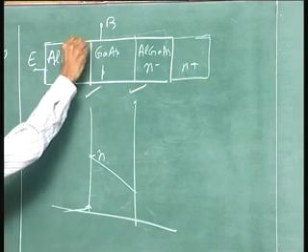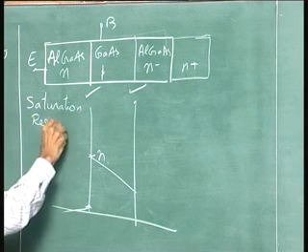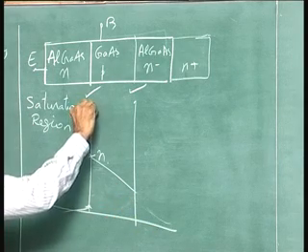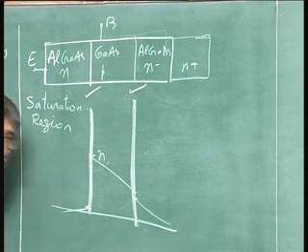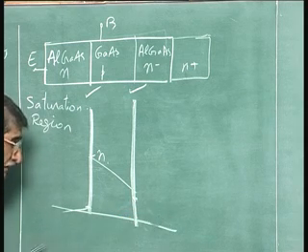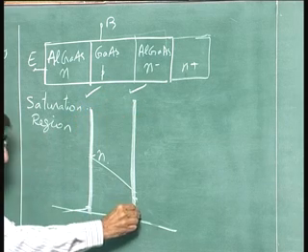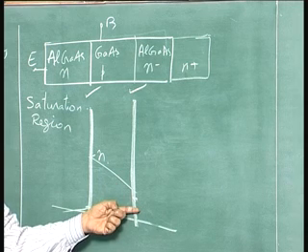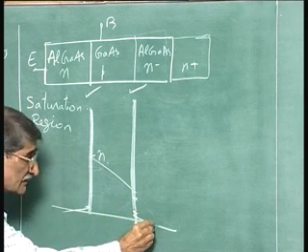So, if it is forward biased, the device is in the saturation region. If this were the same gallium arsenide, you would have got the hole concentration reaching like this. Of course, I just draw a small region there to signify the transition region. You would have got high concentration hole injection like that if it is a narrower band gap material. If it is wide band gap material, what happens here? Same thing. Hole injection from the NP region to the N region when it is forward biased is very, very small, because the boundary value here, Pn0, the P in the N region, is related to Ni squared. Ni squared is small because it is wide band gap material. So, you will have very small injection there.